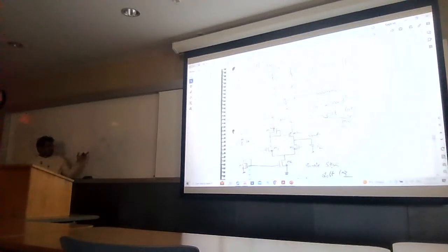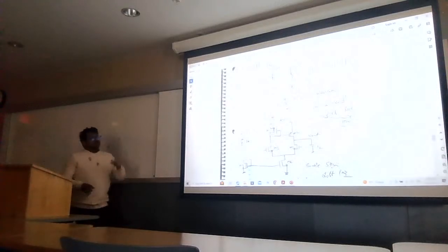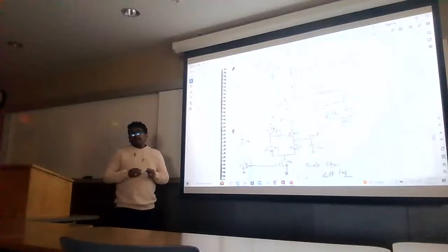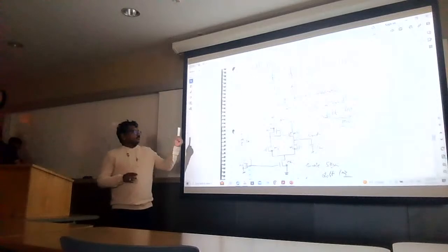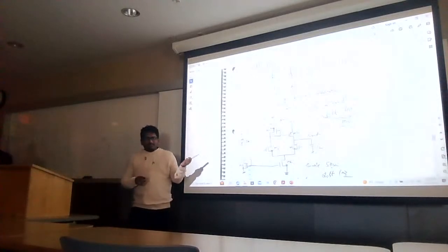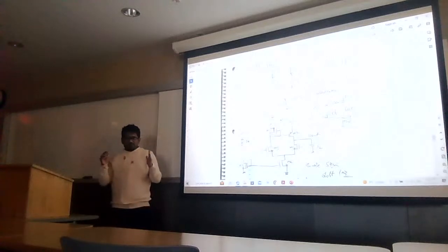So if we apply a differential signal here, then, analog signals are very susceptible to environmental noise. If any noise comes in, the beauty of the circuit is that it internally works to reduce the noise. It can subtract the common mode noise. So we need this type of differential amplifier to deal with analog circuits. I think you remember that at the beginning of this presentation, I gave you some examples of block diagrams of analog systems.